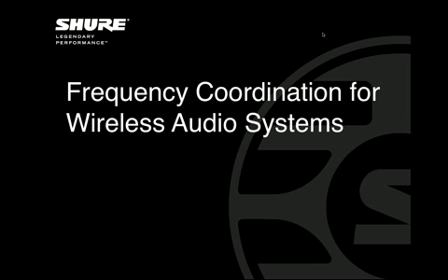And as with last month's topic as well, this is stuff that applies really when we're talking about larger systems with a lot more channels on the air. Getting one wireless microphone system to work, there's usually not too much trick to it. 2, not too much more difficult. As soon as you start getting to 3 or more, all of these things like frequency coordination and antenna placement start to become more and more important.